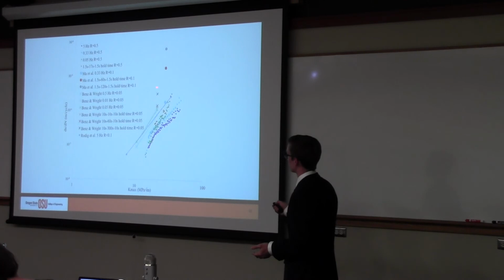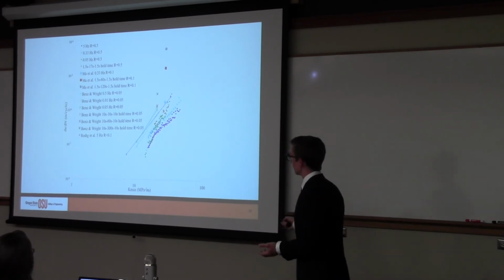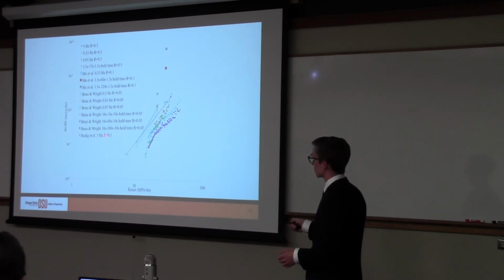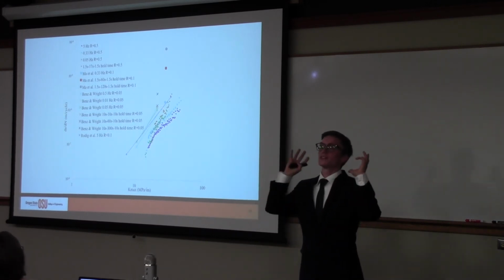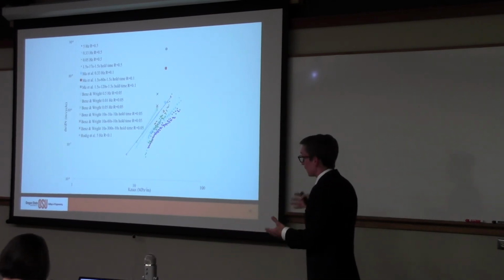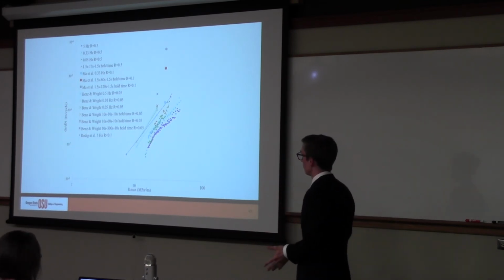And what we see from the limited data that we've gathered or been able to compare to in the literature is that yes, these last data points, the gray ones, and I labeled them gray for a reason, might not be so reliable. But what is reliable is that Kmax of 23 or so, or if you want to look at delta K, 11.5, is where the transition happens, even at a load ratio of 0.1. So we've uncovered this persistent trend in crack growth rates that allows designers of next generation nuclear plants and the intermediate heat exchanger in general